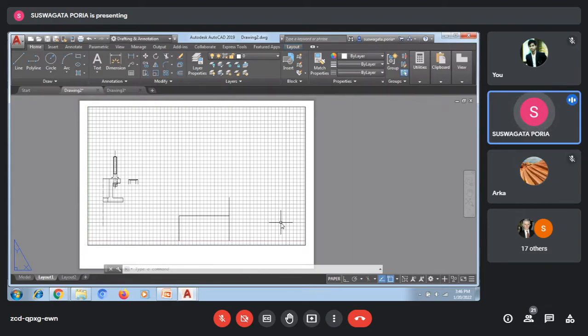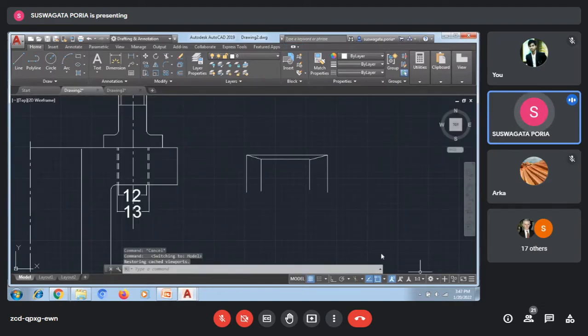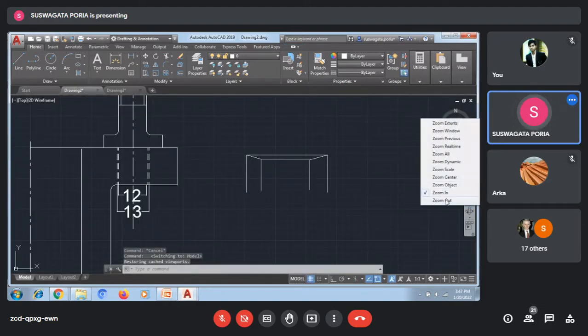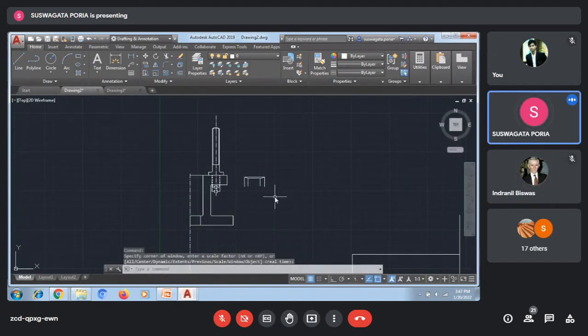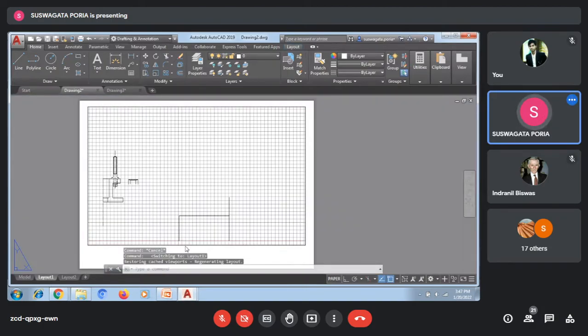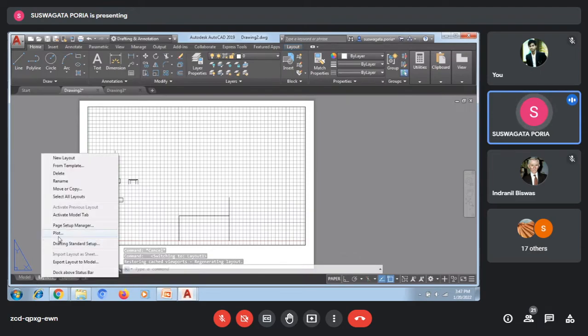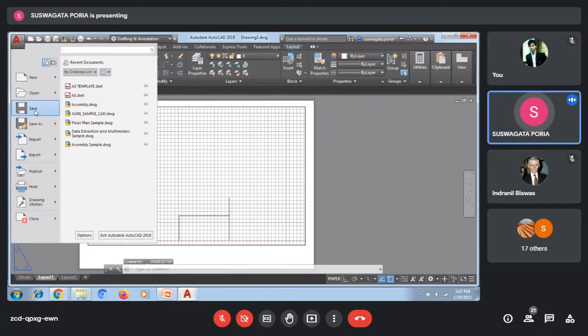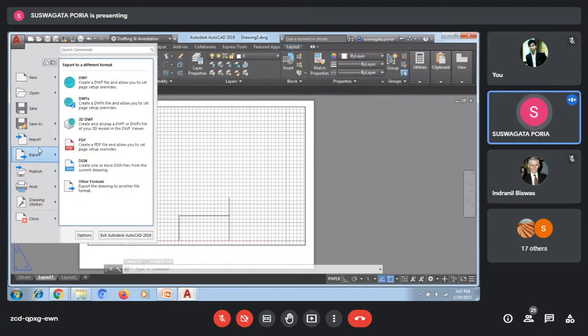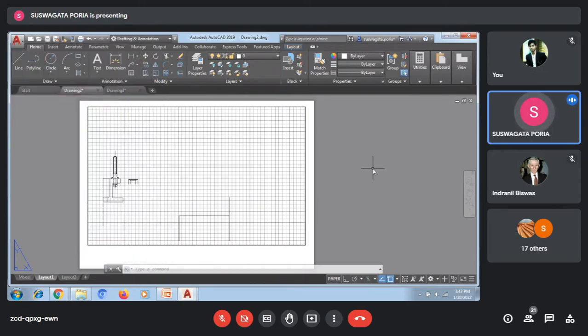So that when you do the drawing, suppose you have done this drawing, then you will bring that template here and automatically you will put it into layout, and from the layout, if everything is fine, you will check from the page setup manager what you are trying, plot size is landscape, drawing to PDF or not plotter. When everything is fine, then you will go here and export it as PDF and you will submit that PDF with title block in the assignment section.